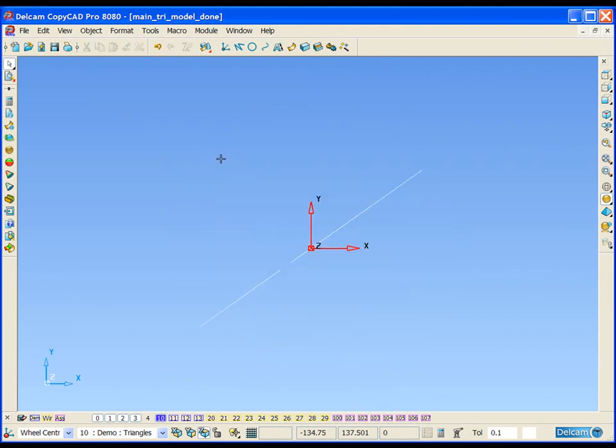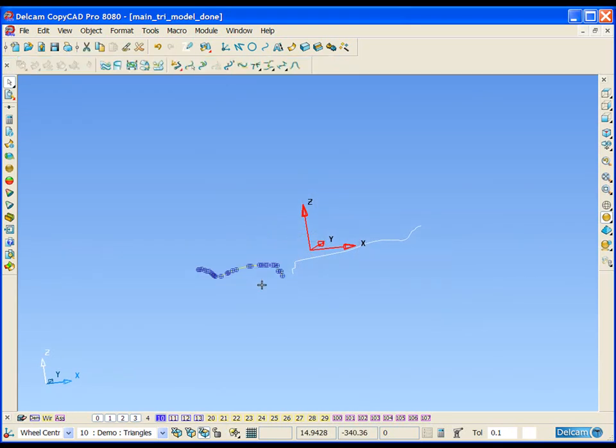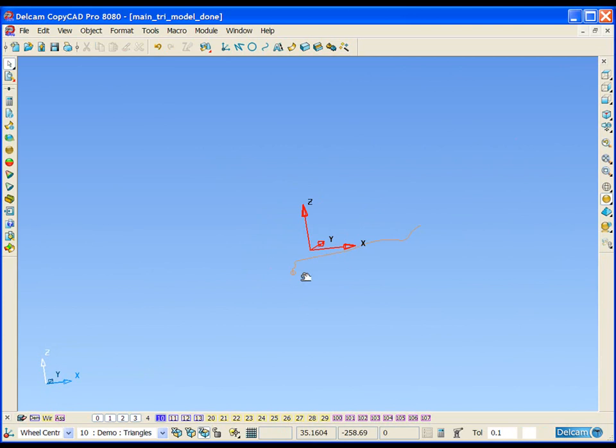If we blank the triangle model from view now and rotate this around, we can see the piece of wireframe that has been captured. We can delete this piece as it won't be needed. If we turn on level 11, we can see we also have a piece of wireframe representative of the maximum values of our front face. So this in effect will be a design constraint. The front face of the alloy wheel cannot exceed the level of this piece of wireframe.